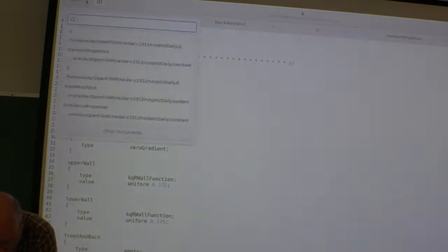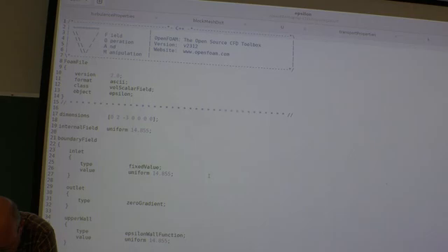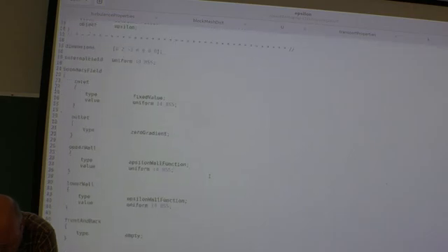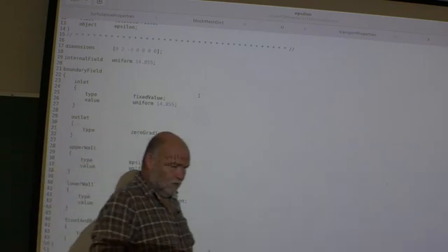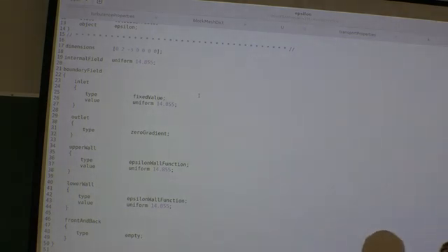Same goes with the epsilon. Where do we have epsilon? Here. Again, they give the internal field a value. That might be smart. If you don't do that, you risk that the turbulence will never start to grow. Here, quite high Reynolds number, we have a quite strong driving force in the system.